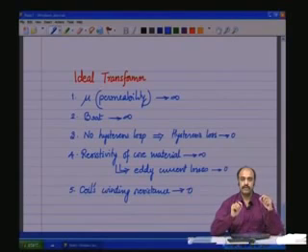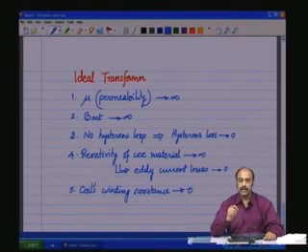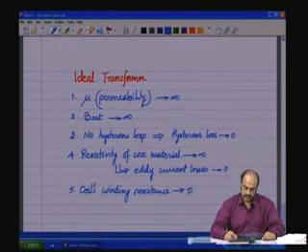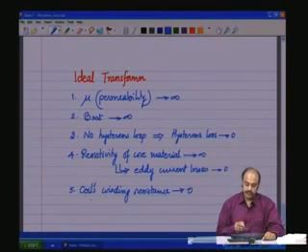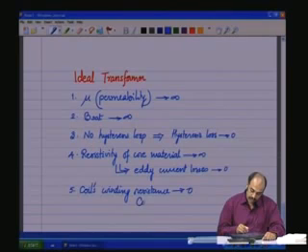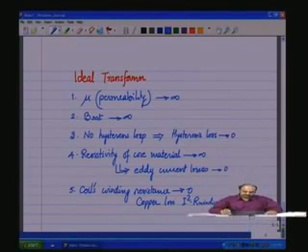So, therefore, if there is a winding of finite number of turns, the resistance is also finite, and therefore, there is going to be I square R loss. So, if the coil's winding resistance is tending to 0, there is no copper loss. The copper loss is I square into R winding, will also tend to 0.